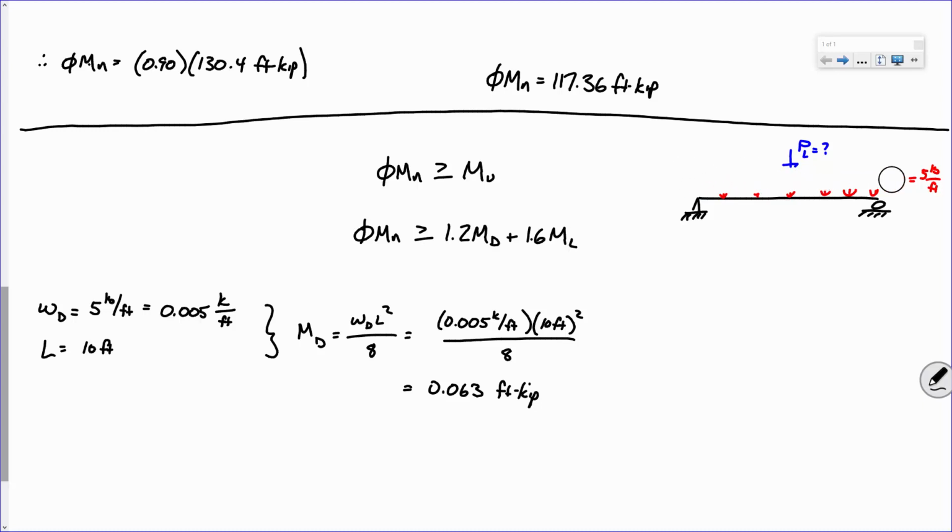Let's do a little bit of basic structural analysis here. Let's say I have a single point load at midspan. What are the reactions going to be? P over 2, right? That's P over 2, that's P over 2. And this dimension here, that's L over 2, that's L over 2, right?